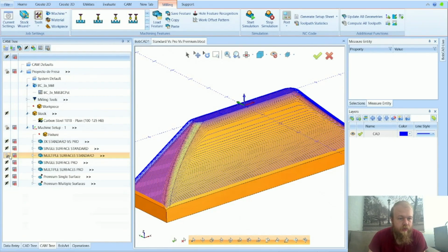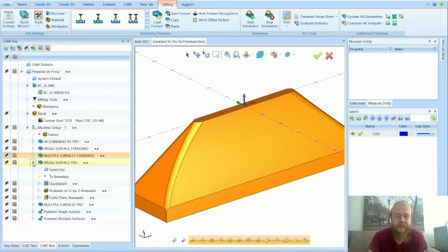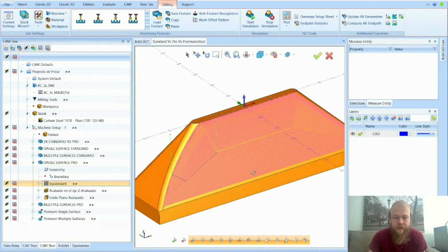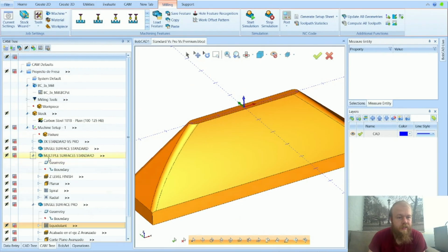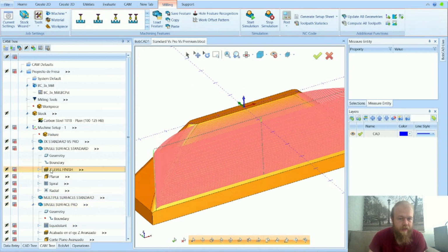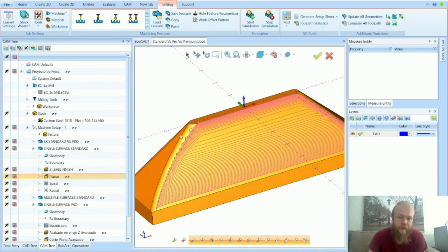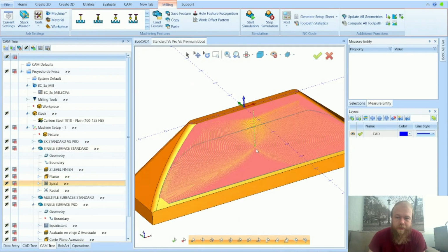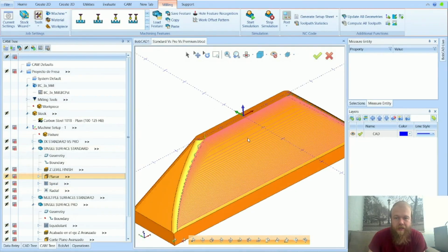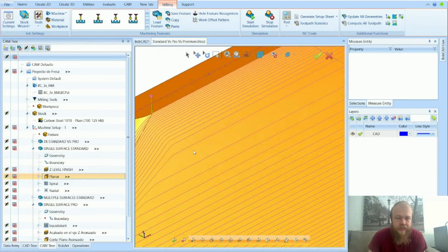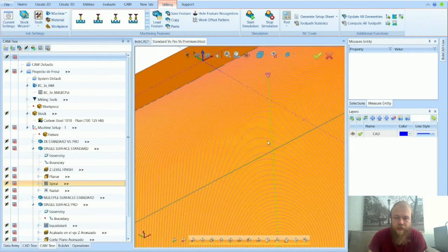We'll get into the 3-axis Pro to follow along the single surface here. And then the 3-axis Pro to follow along the 3D model. So the best one in the single surface and standard, I would say probably would be either the planar looks decent. The spiral actually looks pretty good with the boundary, but I would rather just go back and forth along the surface here. But again, you can see like the larger step over, the spiral toolpath gets kind of weird up at the top here.